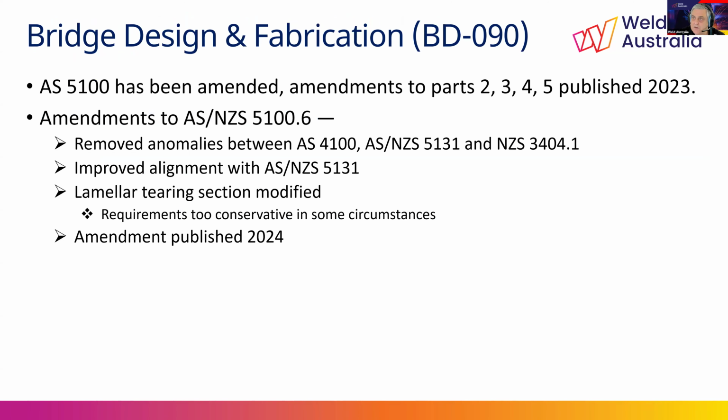Now, the Bridge Design Standard 5100 Part 6 has been amended to remove anomalies between it and 4100 and 5131, and also the New Zealand Standard 3404 Part 1. Of particular note, the provisions for the management of lamellar tearing were seen to be too conservative in some circumstances, and the provisions have been modified to address this in 5100.